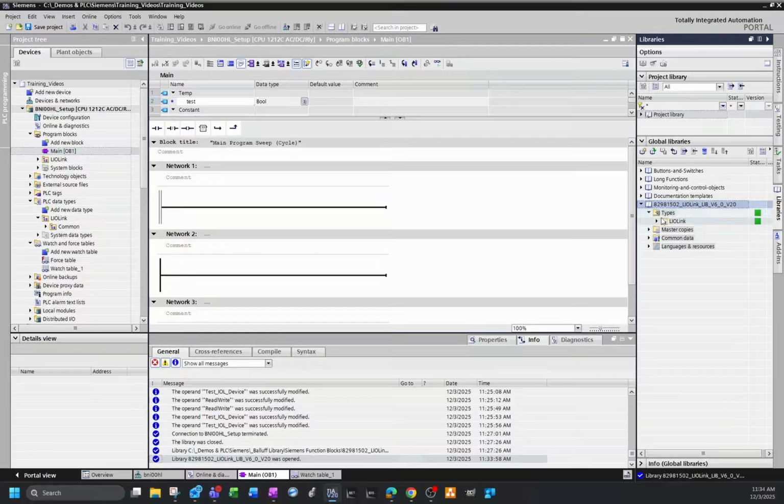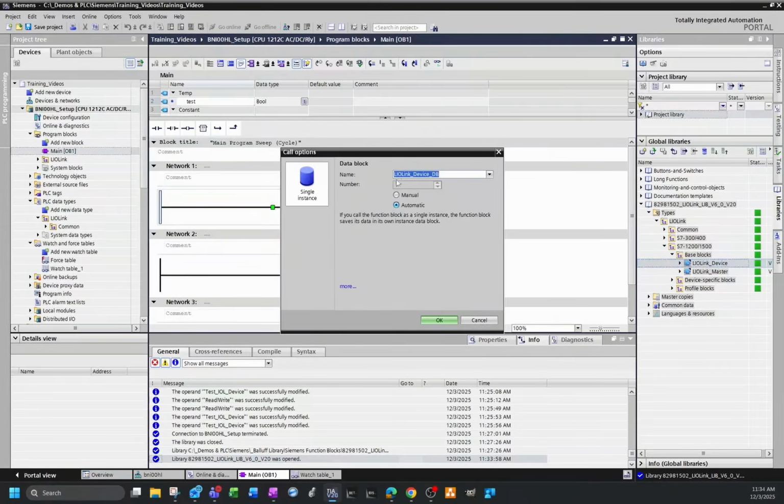devices. To do this, I'll navigate to the Types section and then select IO Link as the device type. From there, I need to specify the controller settings, family, base blocks, and finally, the IO Link device itself. I'll drag the selected IO Link device onto my program ladder and create it with a default name.